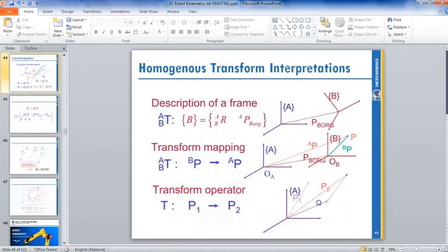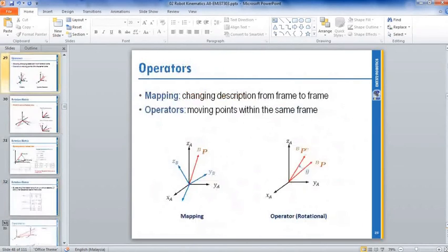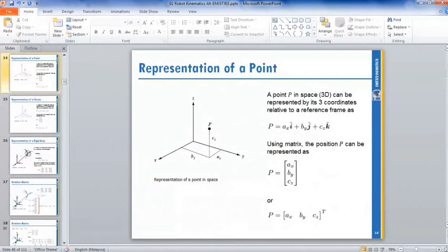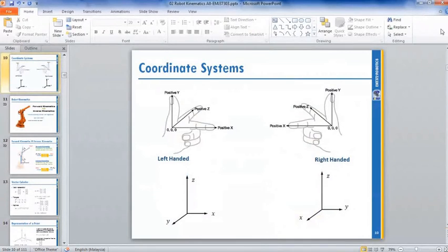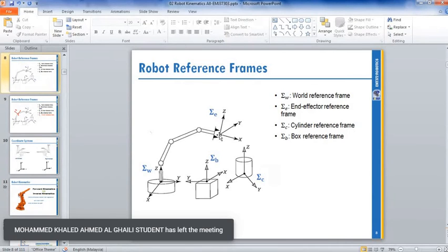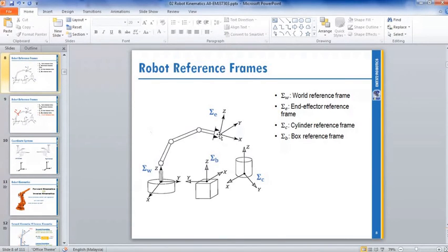It sits here. We imagine at the tip of the gripper, like this. So we rotate Z 90 degree, rotate Y 90 degree, and then he said move X4, Y -3, and then Z 7. Move X, Y, Z from this point.